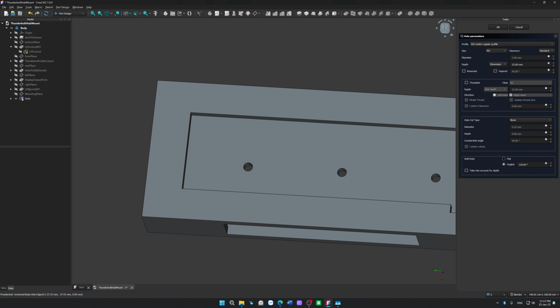Let me check the dimension. Length doesn't matter. Would we do all through? So the K is only 2mm, right? We need to select the countersink first. Cutout tab, countersink. Diameter of the countersink. DK. Yep, DK is 5.3mm.